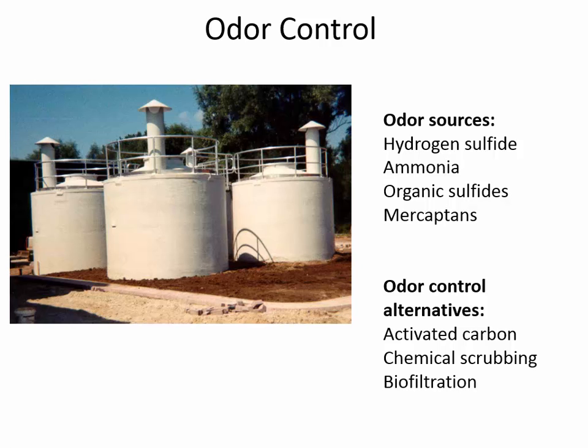In this case, the bad smells are being captured by the activated carbon before the cleaned air is emitted out into the environment. Another way to do it besides activated carbon is to have a chemical scrubbing, which would be sort of like a spray of water into the polluted air, and the water that's being sprayed has a mix of chemicals that react with the sulfur containing compounds.